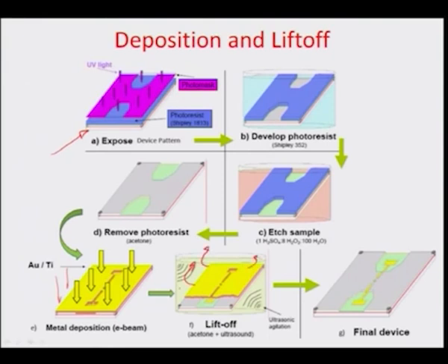So, wherever the vias were open on the resist due to the second lithography step, there would be a remnant film staying back, because titanium is a very good agent which cross bonds silicon oxide or dioxide to gold. Okay. So, basically it is a sort of adhesion layer or adhesion promotion layer.